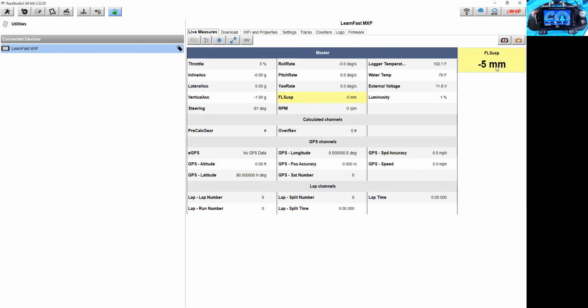And we were doing all of our ride height adjustments based on some math I had done ahead of time and knowing exactly when those A-arms were touching those bump stops, and it shortened up the amount of work that we had to do and to get the car right very, very quickly. And again, while it is a suspension sensor and it was measuring it, we were not doing histograms and velocities and all the different things. We were using it for a very, very accurate ride height sensor. It was kind of a cool way of using it.